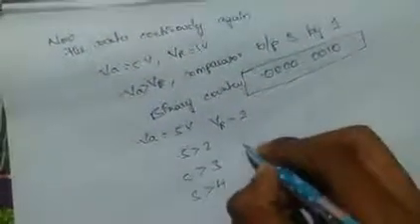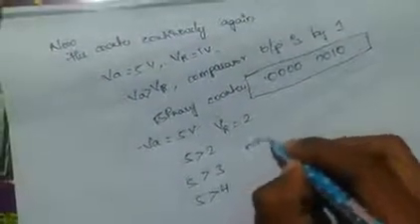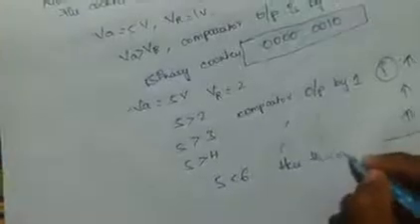Here the comparator generates an output and the binary counter is increased by 1 again. So here VA is 5 and VR becomes 6, that is VA is less than VR. Then the comparator output is 0.